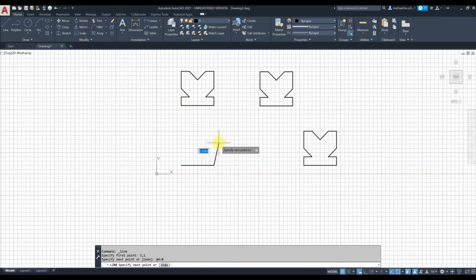We're gonna use so that's polar, right? So length 1, tab key, that's the angle 90 degrees, right? Again, length is 1, press tab key, angle 180 degrees. Okay, for next one we're gonna use Cartesian coordinates.